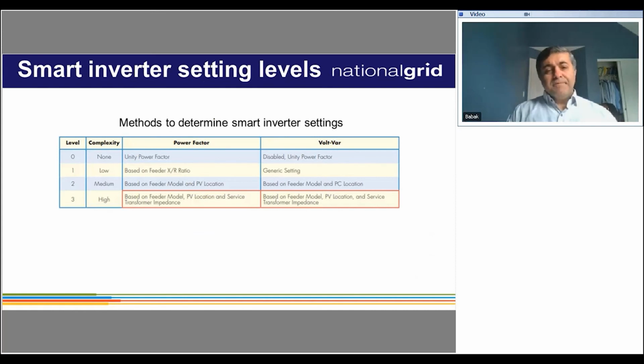So what I'm going to do in the next, I think, 3 slides is address one of the biggest questions we have on the utility side: are volt-var settings, power factor settings, or reactive power settings all impacting the system power quality? Is it just one setting that applies for the entire circuit or entire area? The answer is no. Each power factor setting is location specific. Each volt-var setting is location specific. So you can't have one power factor working for all the DERs in your system.